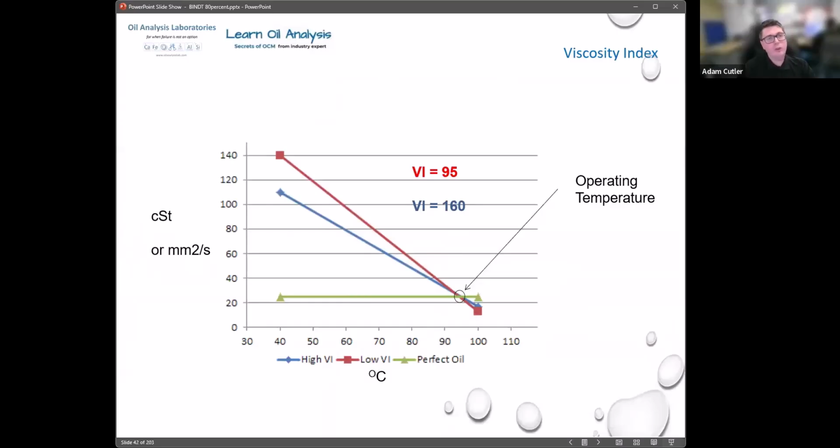So when we talk about an oil, it's important to know the temperature that we're measuring it at. Because you'll notice when you've done your own cooking at home, you pour a bit of olive oil in a pan, you turn on the heat, and soon what seems quite thick oil in the pan is zipping around. It's gone very, very thin quite fast. And that's because that's got a low VI, so it's going from a thick product to a thin product very quickly with an increase in temperature.